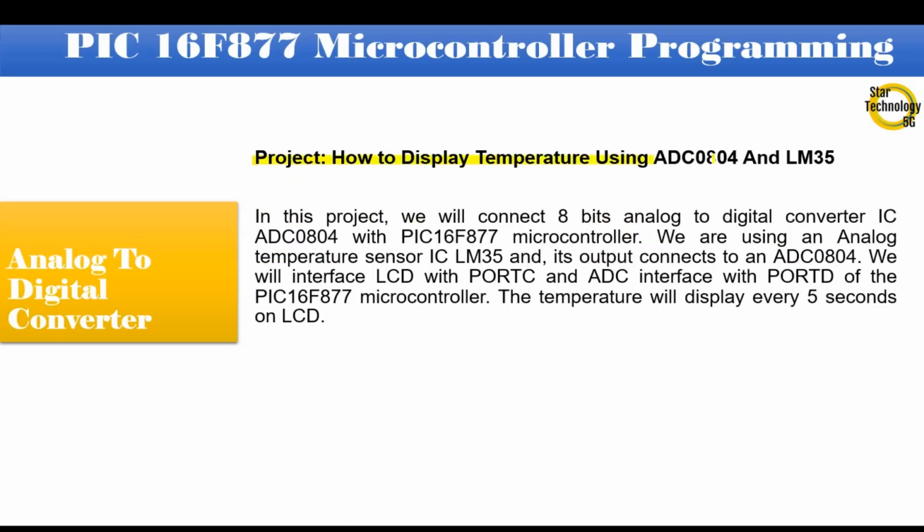Project. How to display temperature using ADC0804 and LM35. In this project, we will connect the 8-bit analog to digital converter IC ADC0804 with the PIC16F877 microcontroller. We are using an analog temperature sensor IC LM35 and its output connects to the ADC0804. We will interface the LCD with port B and the ADC with port D of the PIC16F877 microcontroller. The temperature will display every 5 seconds on the LCD.